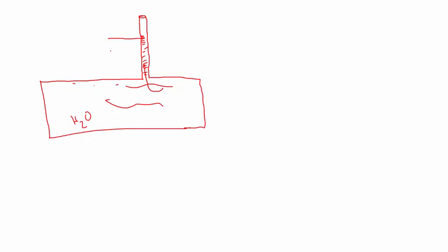Assume that this is H, the height, the equivalent amount of pressure. This piece is called pressure head. Let me explain why this is called pressure head. Assume that I'm interested in the pressure in this tank at this point right here.